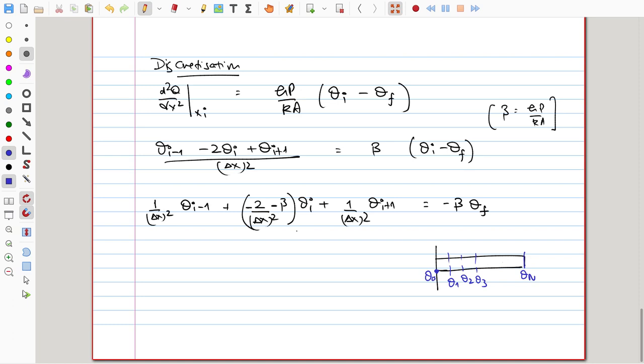So how many unknown thetas are there? N plus 1. You have discretized the problem, so it goes from theta naught all the way to theta n. If you want to find the temperature everywhere, you want to find all the temperature values. Let's for now say that we don't know them. What we will do for the knowledge of boundaries is include that as extra equations. So the total number of thetas is n plus 1 in this situation.